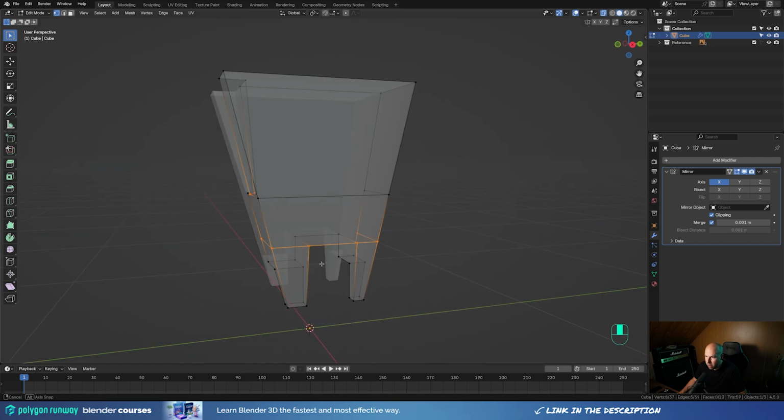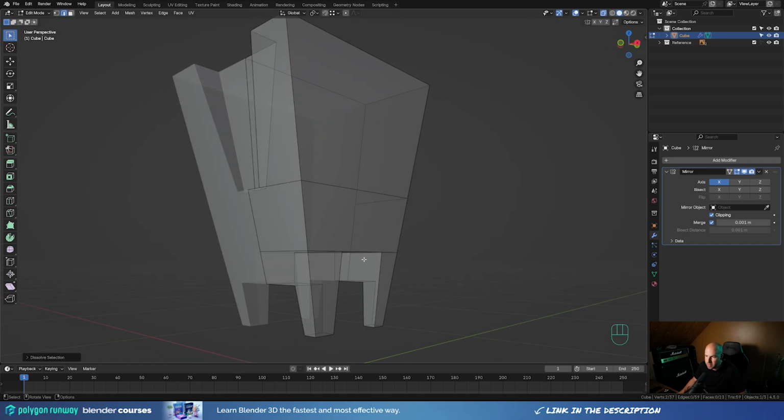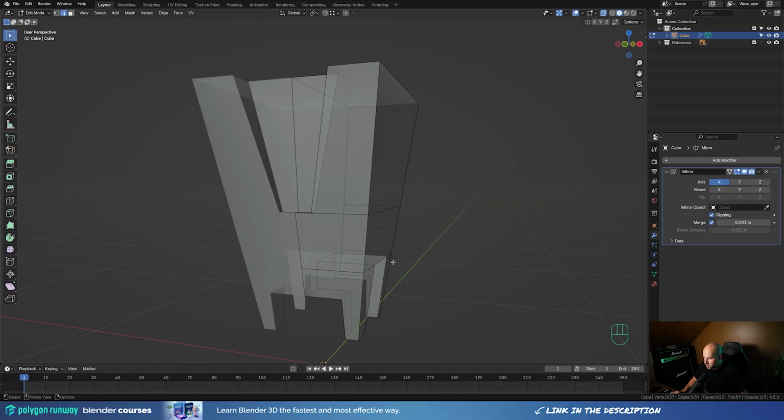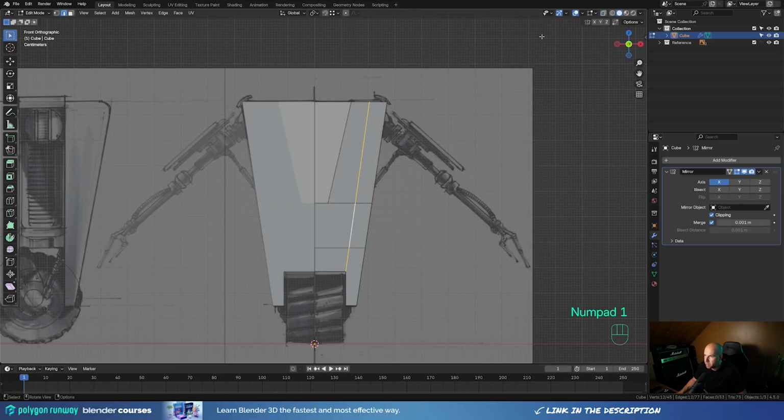So let's figure out how to simplify this even more. And I will leave some of the angles in place. We'll mostly use bevel modifier here anyway, without any subdivision. So let's look from the front by pressing 1 on a numpad, press K again for a knife tool. Let's snap it right here. And we can just do cut like this along that side slope right there. Press C for cut through, confirm and hit enter. And now disable the X-ray view.